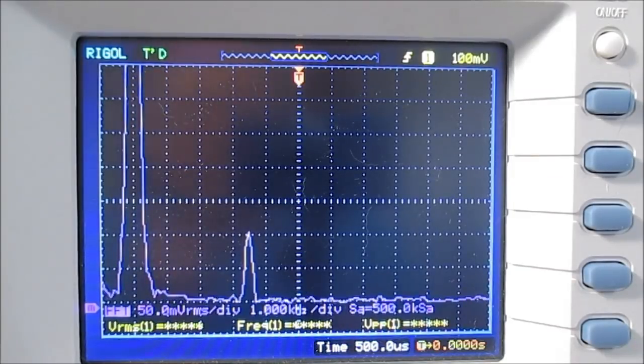Alright, I had to change the battery in the camera. I need a better solution. Maybe like a webcam, something that I don't have to depend on batteries for video shooting. But anyhow, what do I mean by below measurable distortion? Well, my oscilloscope can measure down to 0.2%, 0.3% reliably. If I had better equipment, I could certainly measure the actual distortion that the amplifier is making.